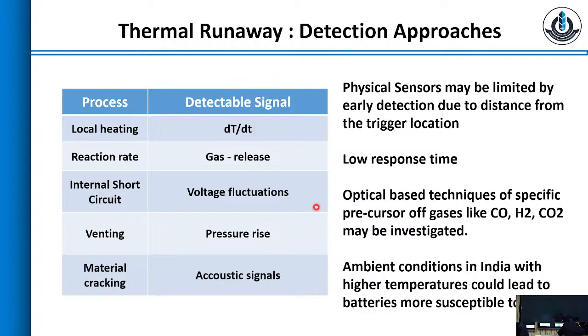What is the optimum temperature inside the battery pack? At 59 degrees, it just starts fading. Typically we try to maintain 40 to 50 degrees Celsius. In summer, our ambient temperature is high, so you need some kind of cooling mechanism.